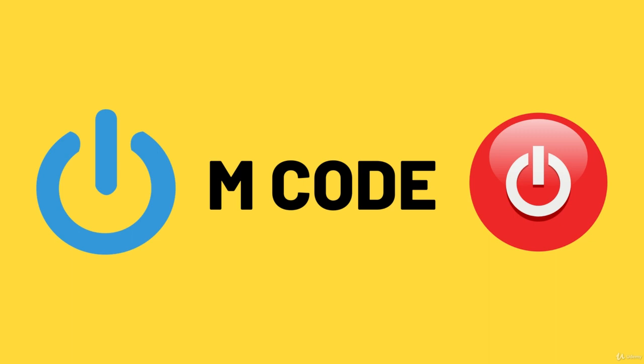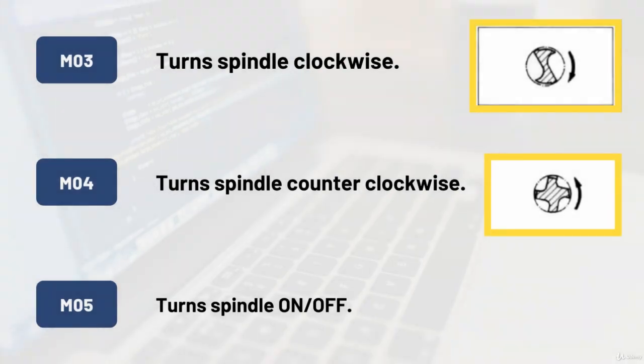M codes are not grouped in categories, although several codes may control the same type of operations, such as M03, M04, and M05, which control the machine tool spindle. M03 turns the spindle clockwise. M04 turns the spindle counterclockwise, and M05 stops the spindle.